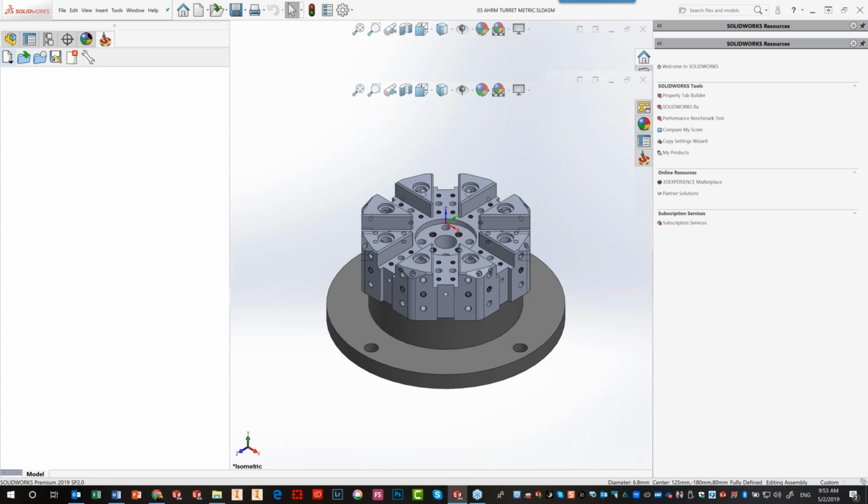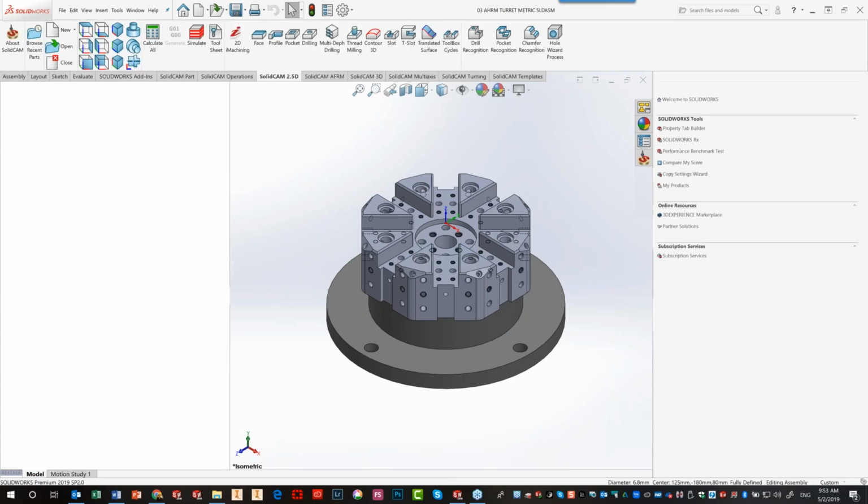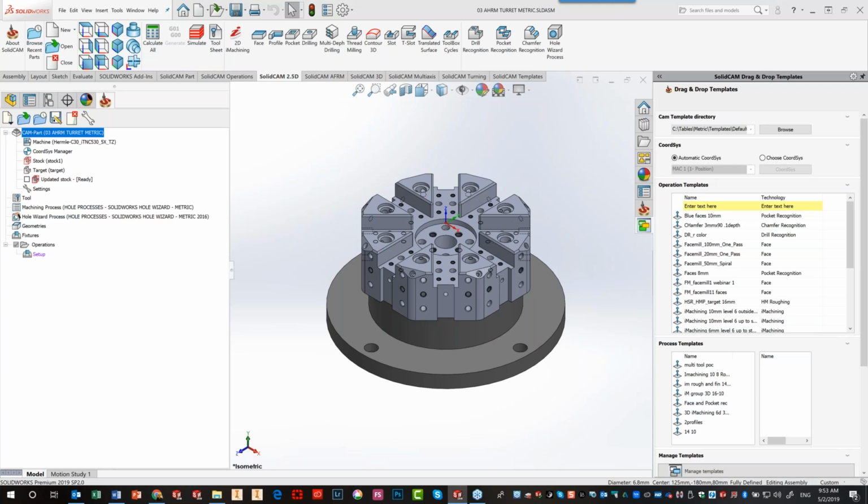Automatic hole recognition and machining is a module that's designed to automatically recognize the holes classified into different shapes and groups, then converts the holes into machinable segments, distributes the machinable segments into all different types of feature sets, and then chooses the proper technology and creates the operations for them. It sounds complicated, but this is actually what it does. It does this all pretty much automatically.